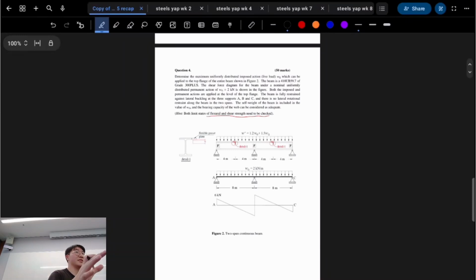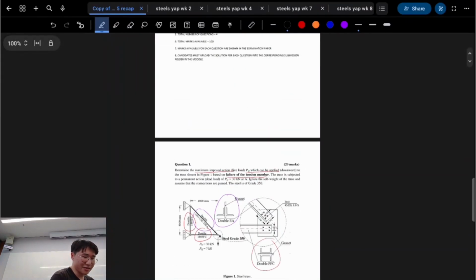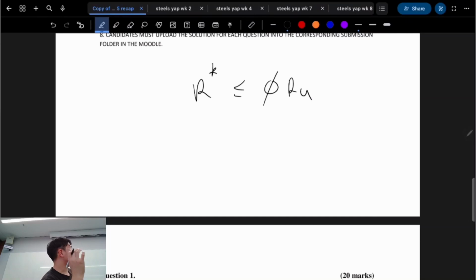And yeah, so that's the whole exam paper. And when you have the algebra to rearrange for the unknown, it just becomes so much harder, right? But when you're looking at any of these loads, let's just call it R. So that could be V, that could be moment, that could be axial capacity N. What we're saying with the capacity equation is that all that weird stuff going on with PQ is on the left-hand side. It's all the external loads happening. When I say capacity, that's the right-hand side.